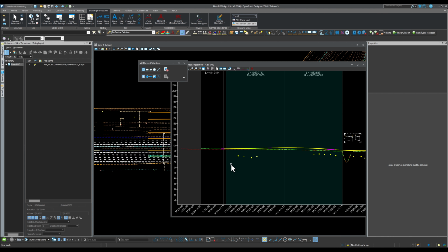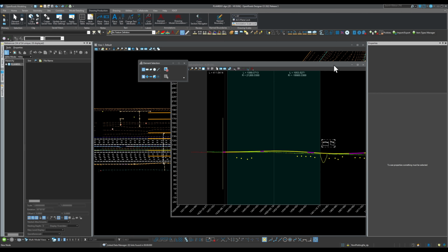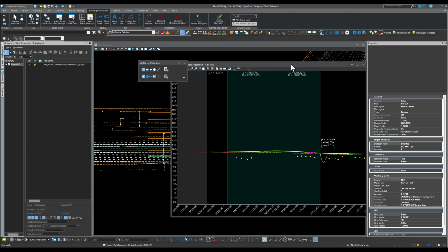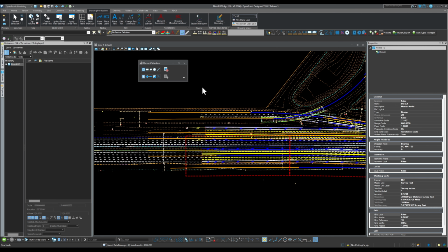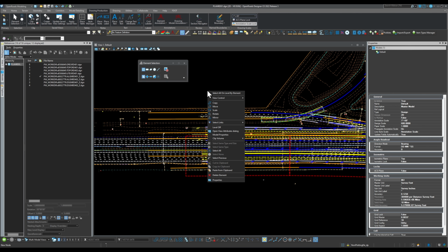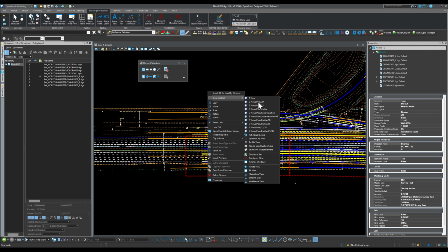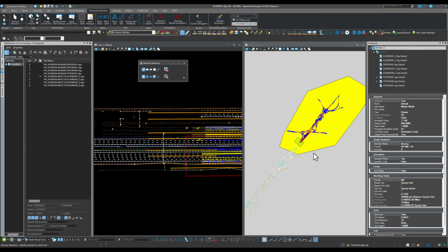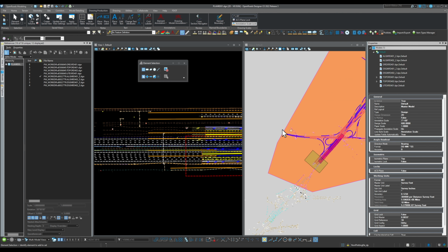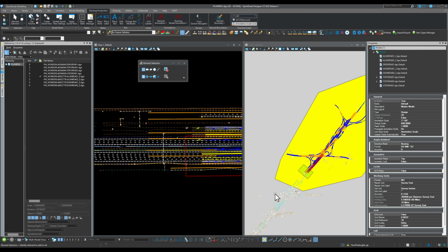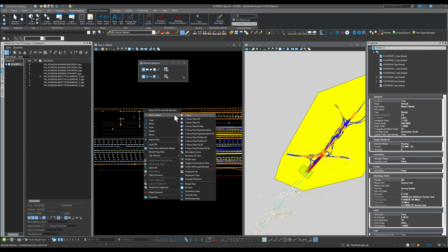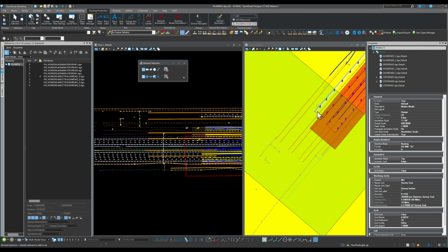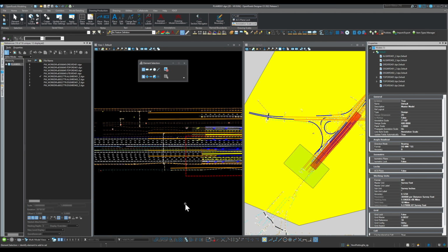How to do that? Reference them. That's it. It's not that hard to do. Because I know most people will think, oh, let's just draw them by hand. Well, yes, that's the easy way. Well, I guess that's the easy way for a brain to think about it, but it's not technically the easy way. Because if you already modeled everything, just attach to the 3D view and they will appear in a profile view. So I tried to create a 3D view, but as you can see, I don't have it.